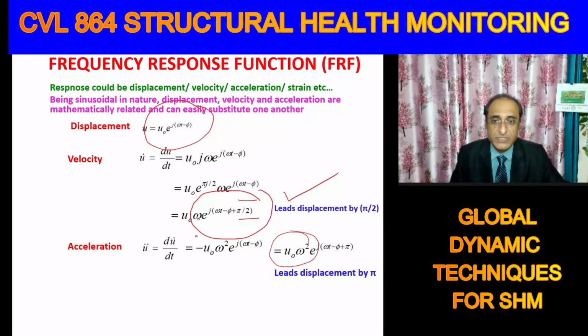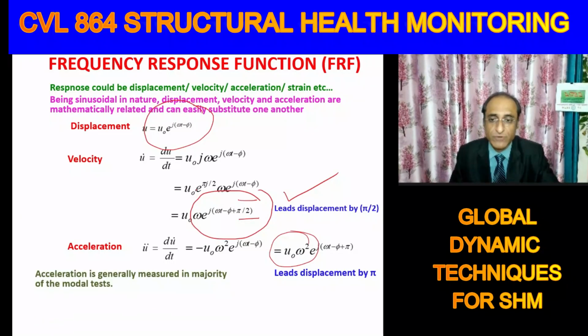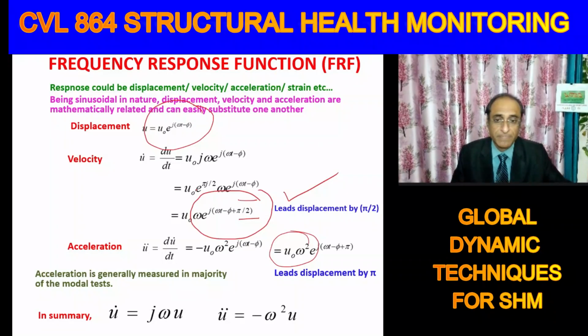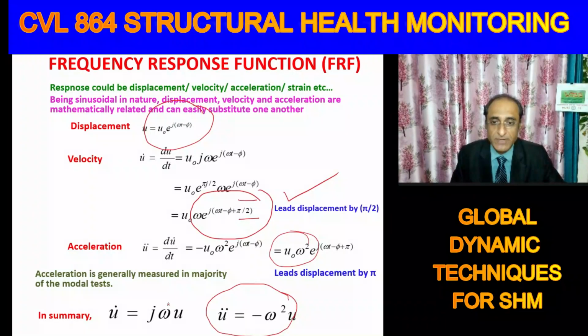But essentially, if you are measuring the peak acceleration and you want displacement instead, all you have to do is find out the frequency of vibration and divide. Then you will get displacement. So they are interconvertible. Usually we measure acceleration and then we can obtain either the velocity or the displacement. To obtain displacement from acceleration, just divide by omega square. To obtain the velocity from the displacement, you just multiply by omega, and you can also obtain velocity from acceleration by dividing by omega. Okay.